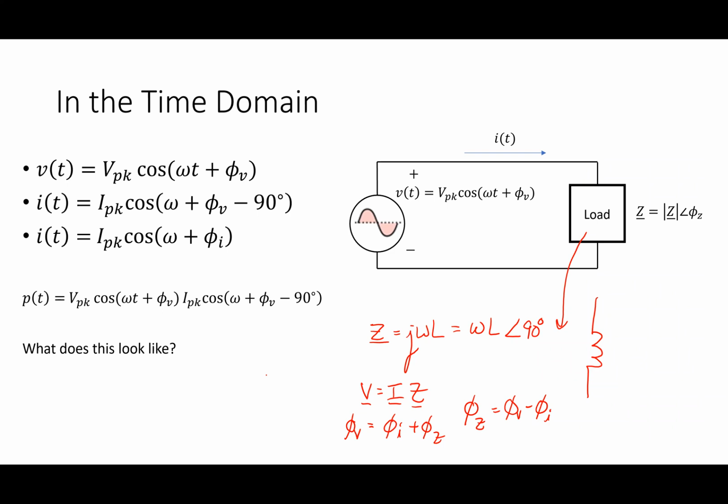So there is real power, which relates to the power that is really going into doing active work. So when I say active work, I mean, if I have a motor and that motor is working at 1 horsepower, then there is 750 watts of real power on average that's going into that motor. If there's a 100-watt light bulb, there's 100 watts of average power going into that thing because there's work happening there.